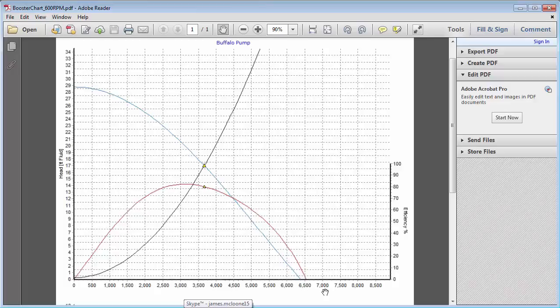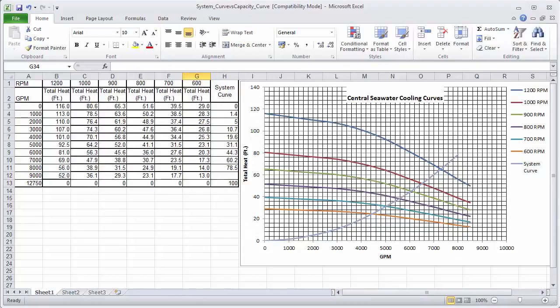On further review of the template Excel file, we identified that in determining the revised pump capacity curve, the affinity laws had only been applied to the head value and not the corresponding flow value. This resulted in the generation of an erroneous curve in Excel, which gave misleading and incorrect pump performance data. When they had considered this adjusted performance data in the cooling system, they were unaware that they had obtained incorrect plant performance results. Luckily, this was identified prior to the completion of the final system design.